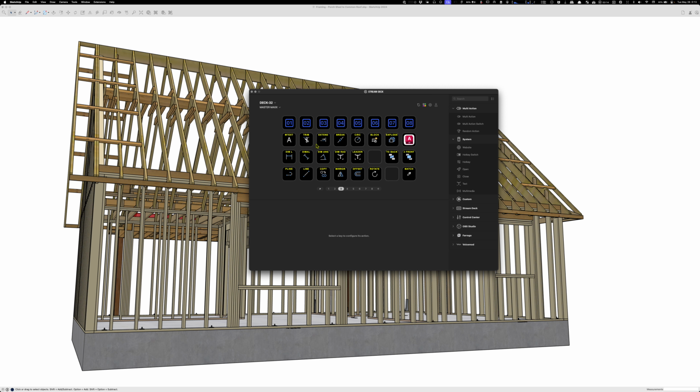And the nice thing about AutoCAD, you ever done AutoCAD where you want to draw a line, so you type the letter L, but then you have to hit enter to choose it? Well, check this out. You push this line button, it generates the letter L, and then it presses enter for you. So when you're in AutoCAD and you just push that, boom, it instantly is ready to go do a line.